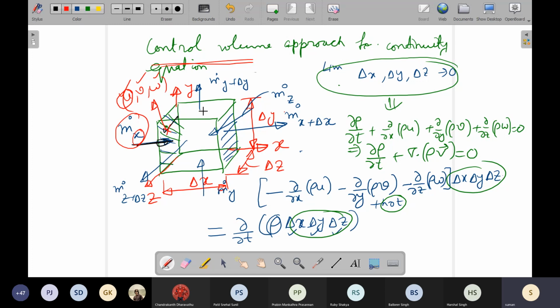Although the velocity vector at the point is very much having coupled vector addition of u, v, and w, for flow rate calculation we are able to decouple by harnessing the mutually independent x, y, and z components, and physically they are mattering because only one component is mattering for flow through a surface which has normal along that component.